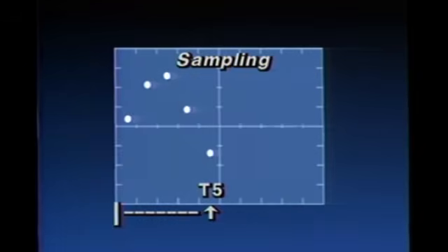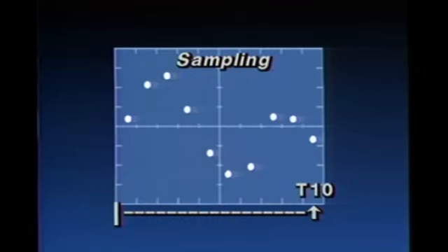The dots you see appearing now show how a DSO would sample the same input signal. In actual practice, these samples would be taken much closer than shown, say 50 to 100 times closer, but the idea is that the samples are taken at very specific times.